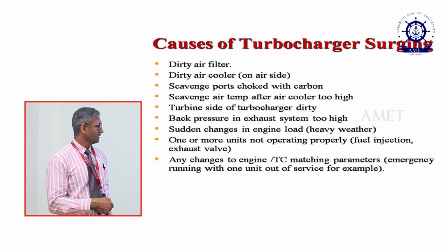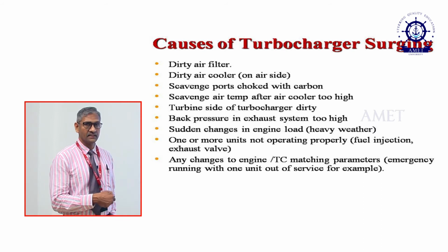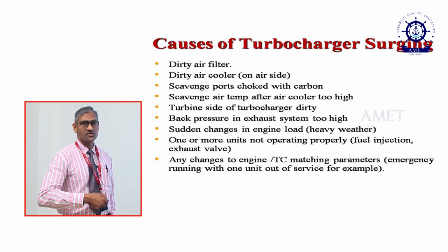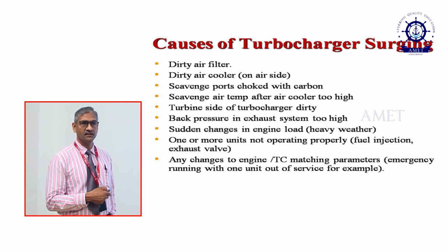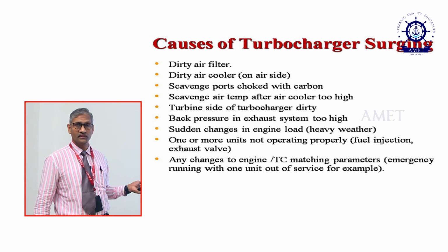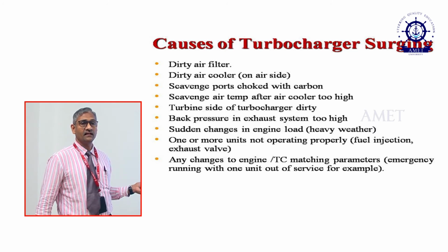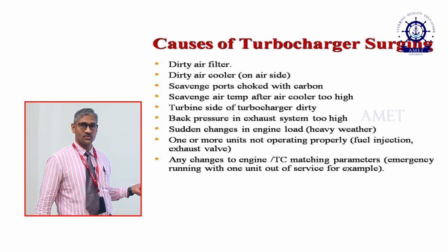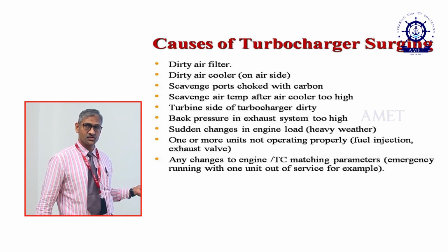So, if there are multiple turbochargers on the engine and they have sudden snorting, which is called surging action, then you need to look at it from a different perspective. There could be something wrong with the fuel that you are supplying, or it could be that the exhaust gas passages are choked, or the exhaust turbine itself is choked.